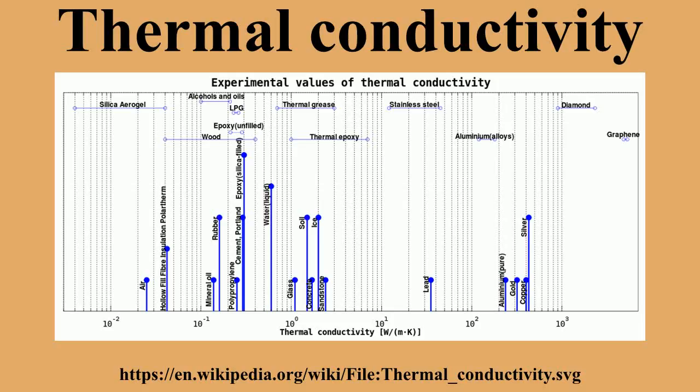Other units which are closely related to the thermal conductivity are in common use in the construction and textile industries. The construction industry makes use of units such as the R value and the U value. Although related to the thermal conductivity of a material used in an insulation product, R and U values are dependent on the thickness of the product. Likewise, the textile industry has several units including the TOG and the CLO, which express thermal resistance of a material in a way analogous to the R values used in the construction industry.